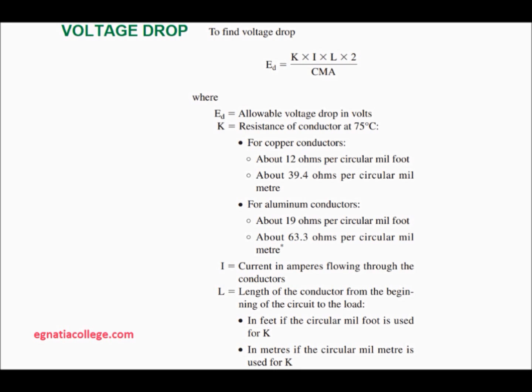A simple formula for calculating voltage drop on single-phase systems considers only the direct current, DC, resistance of the conductors and the temperature of the conductor. The more accurate formulas consider alternating current, AC, resistance, reactance, three-phase installations, temperature, and spacing in metal conduit and in non-metallic conduit.